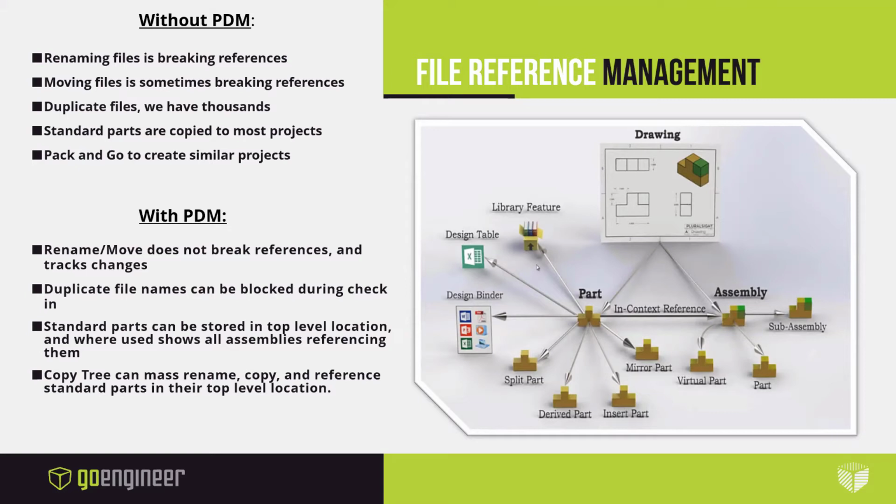So without PDM, there is a SolidWorks rename function, generally in your right-click menu, and that's actually using Windows Explorer or SolidWorks Explorer DLLs to track those changes. The downside of that is that it's got to go actually open with API in the back end all of those files and update the file headers. So a rename or a move through that on a large data set or a widely used part can be very time consuming. Oh, it's extremely time consuming.